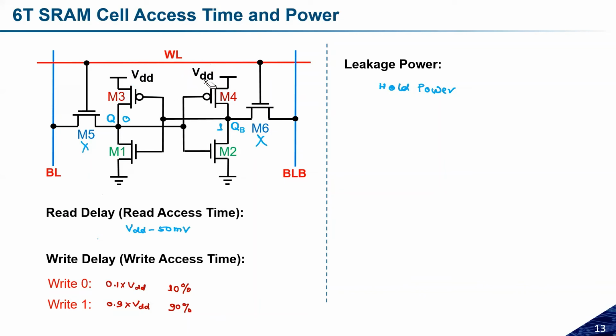On the Cadence tool, you can directly measure it: if you have the supply voltage, put in all these combinations for BL, BLB and the word line, and then see what power the supply voltage is drawing. So you can directly calculate it. This is very small, right? Because there are only 2 inverters and only one inverter is switched on.